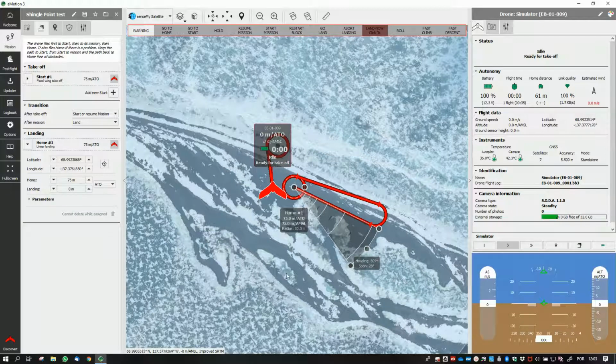It will depend a bit on whether these are lakes or have water or not. But the problem is that over surfaces with water, the distance measuring system does not work well, so you should avoid flying over water during the landing approach. So in this area, I would really emphasize doing a cone along the beach.